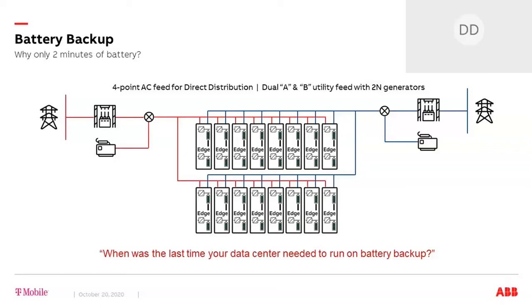Our Florida site is actually in a hurricane-prone area, as you might imagine. We even put all the A-side utility transformers, generators, and electrical gear on the north side of the building, and the B-side equipment is on the south side. There's literally a building between the A and the B systems. It may sound extreme, but the cost to do it was negligible.